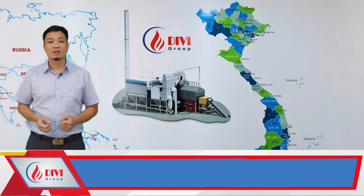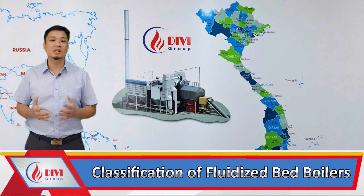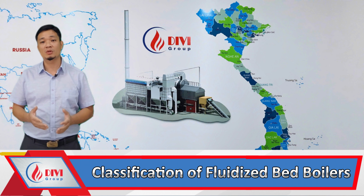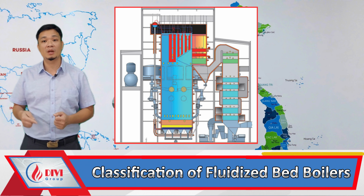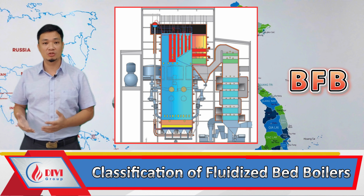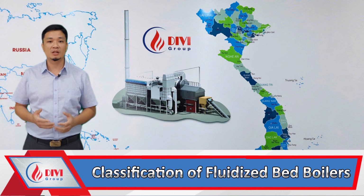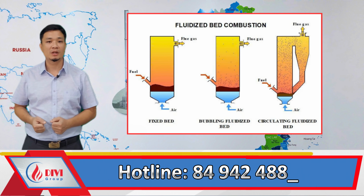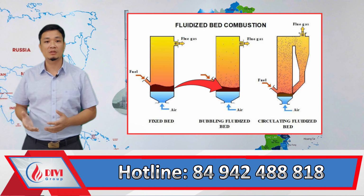Now that we've explored the topic of the fluidized bed and fluidizing material, let's move on to the classification of industrial fluidized bed boilers. Fluidized bed boilers are classified into 2 main types. 1. Bubbling fluidized bed, BFB, boilers. 2. Circulating fluidized bed, CFB, boilers. Both types use a fluidized bed material. In BFB boilers, the fuel remains within the bed until it is fully combusted and light enough to be carried away by the flue gas.